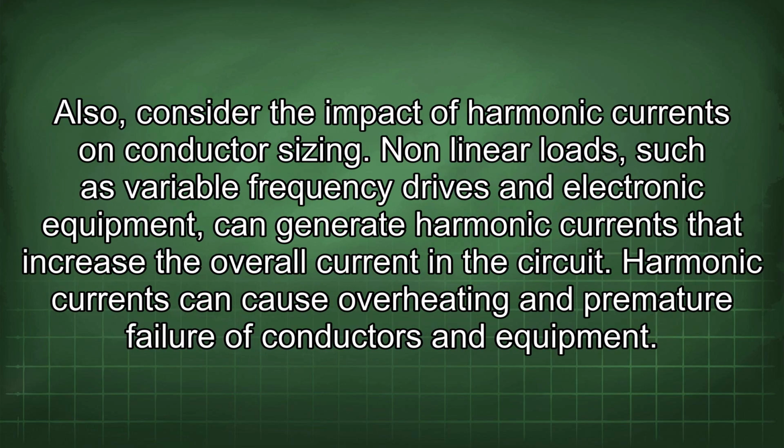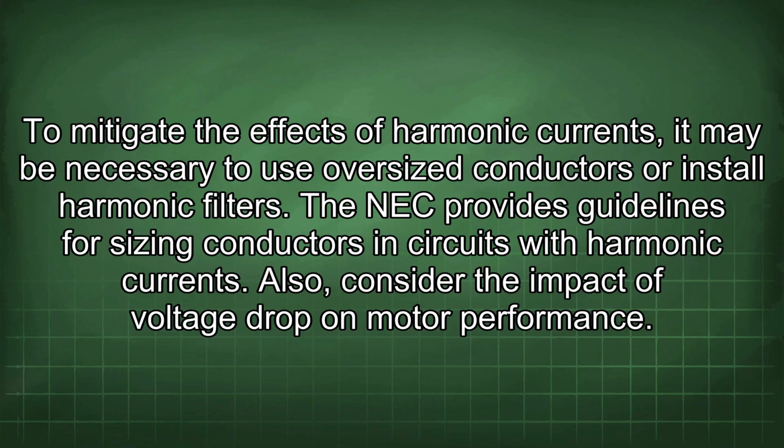Also, consider the impact of harmonic currents on conductor sizing. Nonlinear loads, such as variable frequency drives and electronic equipment, can generate harmonic currents that increase the overall current in the circuit. Harmonic currents can cause overheating and premature failure of conductors and equipment. To mitigate the effects of harmonic currents, it may be necessary to use oversized conductors or install harmonic filters. The NEC provides guidelines for sizing conductors in circuits with harmonic currents.